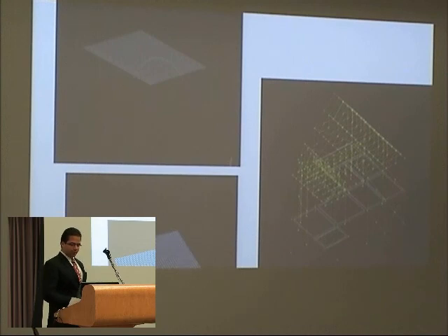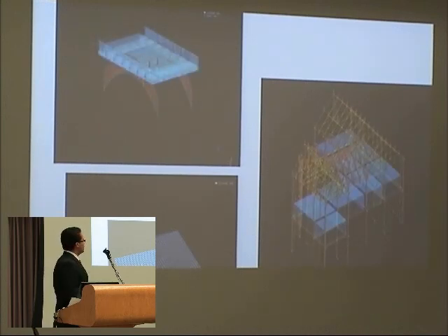So after that, based on the different codes, in the case of the buildings, it would be the ASCE 7-10. In the case of the bridge, it was the AASHTO manual, AASHTO Bridge Design Manual. We came up with all of our loading conditions. Everything was designed according to LRFD specifications, and we applied the loads. These were all hand calculated.